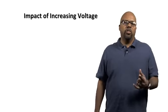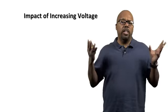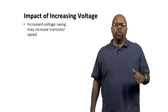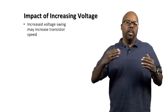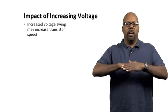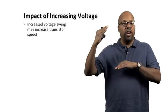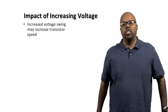So, impact of increasing voltage. So that was overclocking. There's also this kind of overclocking where they talk about increasing the voltage. So what does that do to the chip when you increase the voltage? Well, increased voltage swing. I say voltage swing because you're increasing this swing between the bottom and the top. So 0 volts is the bottom, and the top maybe is 3.3. Maybe I'm going to change it to 3.4, 3.5. You're increasing what's called the voltage swing, the difference between the top and the bottom voltage.